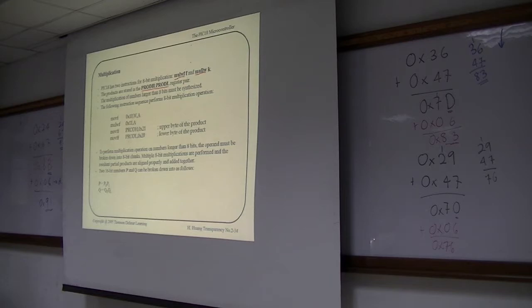So if you want to multiply single byte, in this case you have to use multiply working register with file register because there is no instruction multiply F with F. There's only W with F and also L with W. So in this case, if you want to multiply these two, it is F multiply F. But since we don't have one of it, we have to move it to working register. And then you can perform multiply working register with file register.